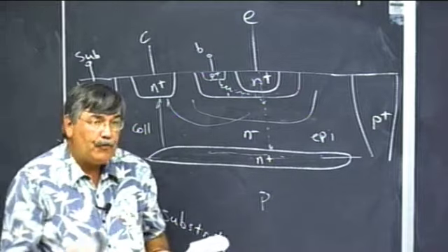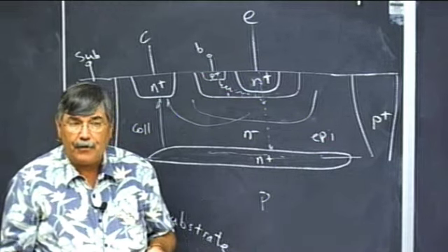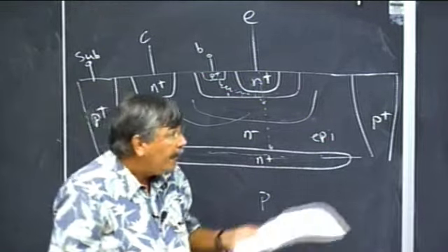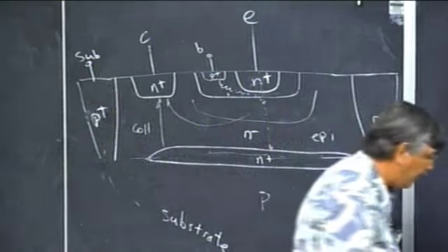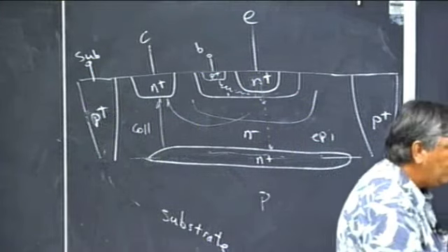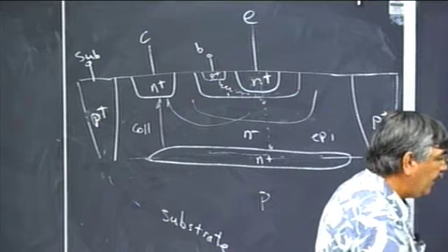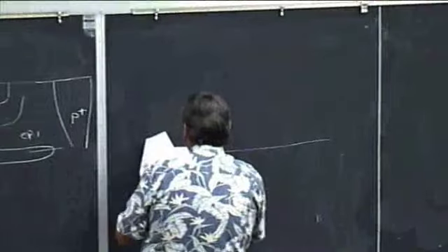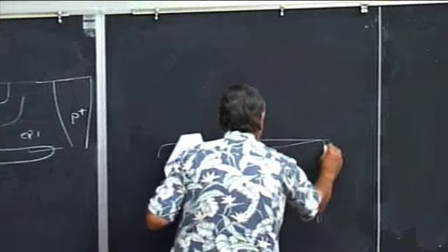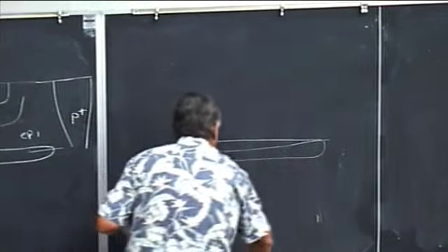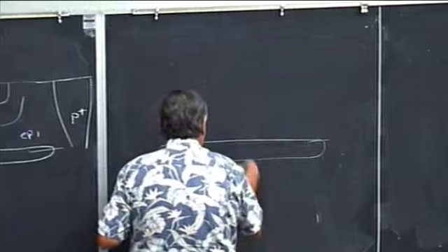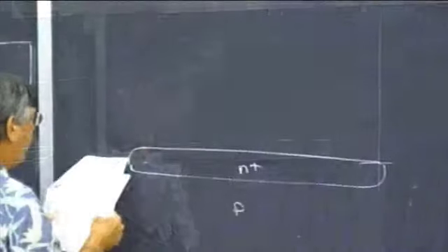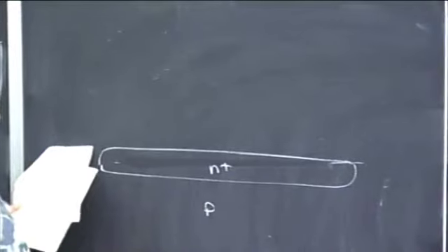Now, I'm giving you still something that's probably a 15-year-old process out of the textbook that is a variation on this one over on board 4. And this is on page 2 of the lecture 4B notes. So we go through a lot of this same stuff. We would start with a P-type substrate. We'll put in a big buried layer. We're going to use some more sophisticated processing. We'll have this N+ going everywhere. And I may have to draw a different picture of this.